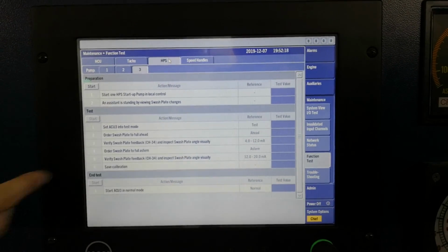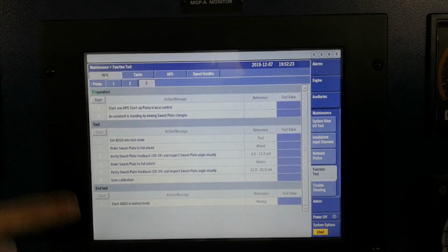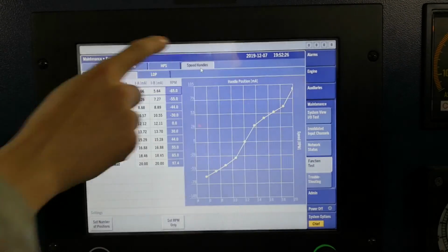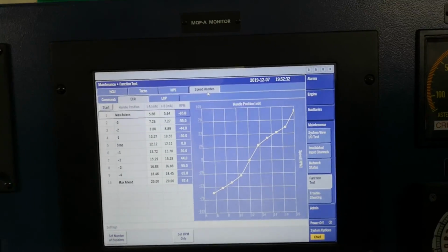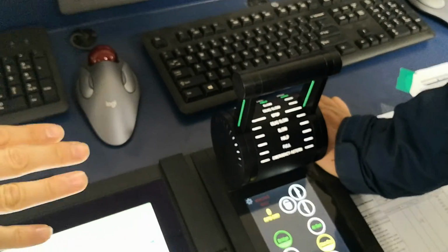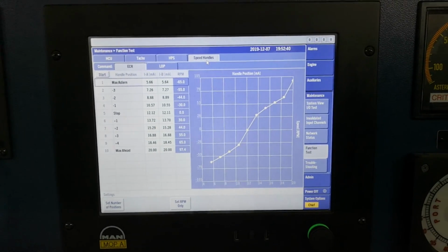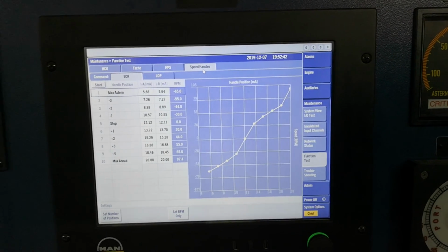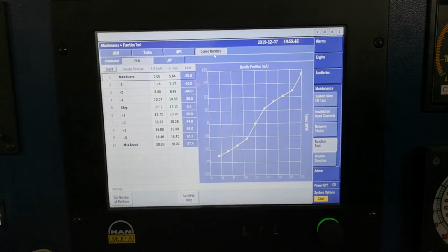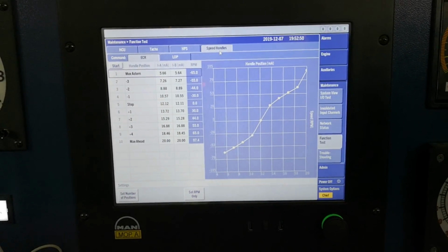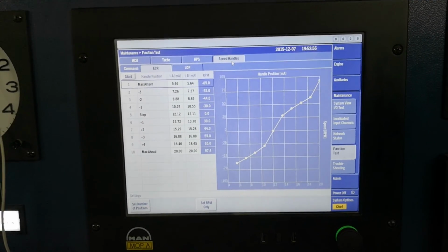Actually for the HPS also, if you change a proportional valve or something, we just recommend this one. It is the same as the HCU and this one. And the speed handle is in the engine ECR. This setting is decided by the main engine. The bridge program is Kongsberg control. Some people always think, okay, ECR has some problem, I will ask Kongsberg. No. This is from the communication between the engine and Kongsberg. So normally the engine side decides this handle. The bridge side is Kongsberg's data. The engine does not relate to it.